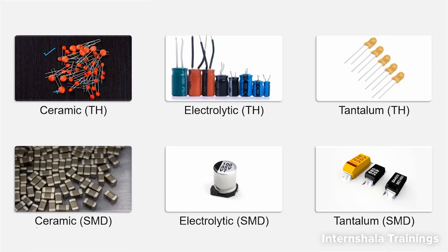And after that, this is the ceramic capacitor with SMD variant. We also call these capacitors MLCC, which stands for multi-layer ceramic chip capacitor. Okay, so these capacitors we are going to use in our design, and we are not going to use these capacitors although they are ceramic, because they are through-hole variant. Instead of that, we are going to use the SMD variant of ceramic capacitor. These capacitors take less space on the PCB compared to these ones. Okay, so these were the ceramic through-hole and SMD capacitors.